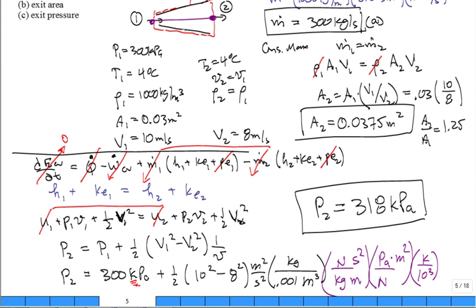What was Bernoulli's equation? Maybe I'll tuck it in right here. Bernoulli. I can't spell his name. No, I think that's close enough. What is his equation along a streamline from point 1 to point 2? The pressure plus 1/2 rho v squared plus rho g z is equal to a constant anywhere along that streamline. Who's seen that one? You've heard of Bernoulli.